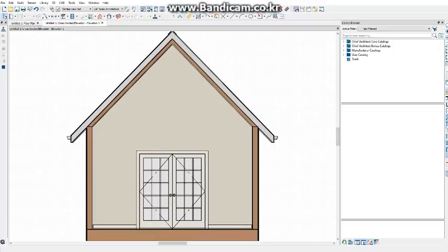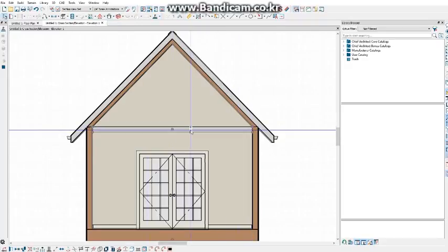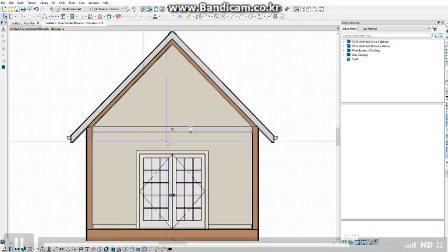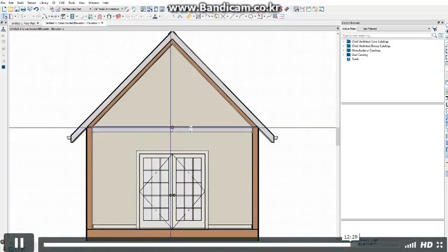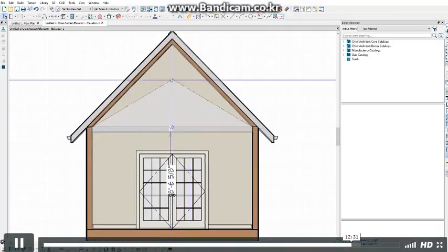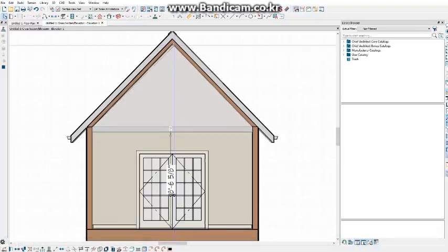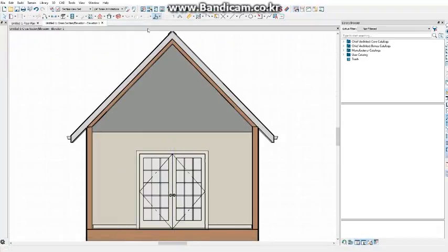You can also create a polyline solid in an elevation or cross-section view. I've created a cross-section elevation view here. We'll go to the Polyline Solid tool and simply click and drag a polyline solid on the wall. Then I'll select the polyline solid and use my editing tools to create a breakpoint or another corner, drag it up to fill the space, go back to my polyline solid tool, create another polyline solid on top of this one,